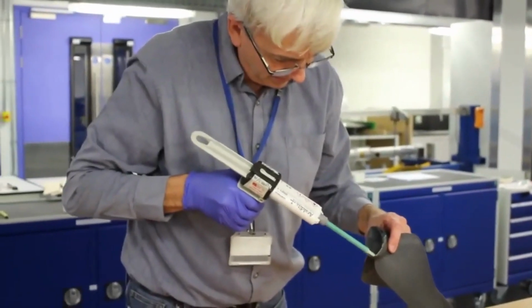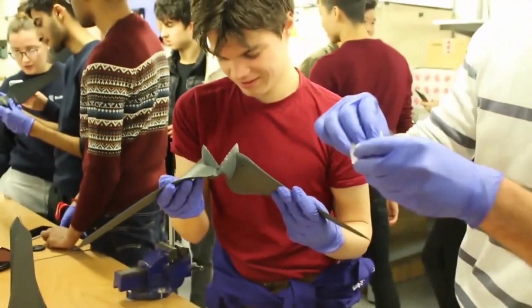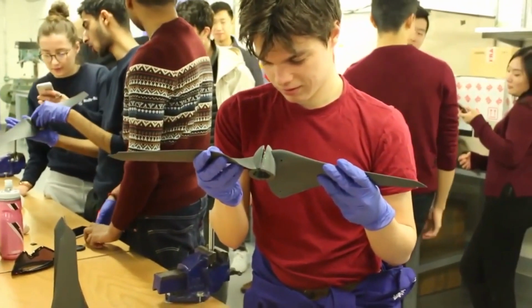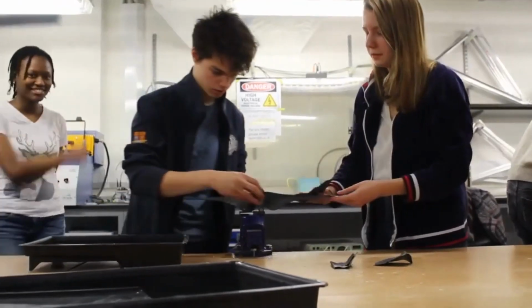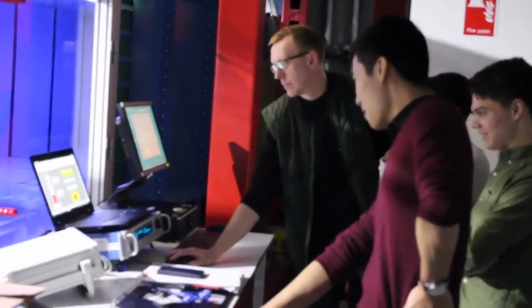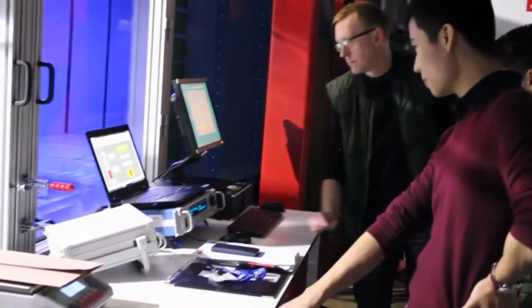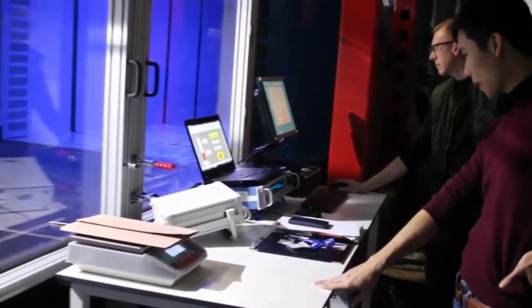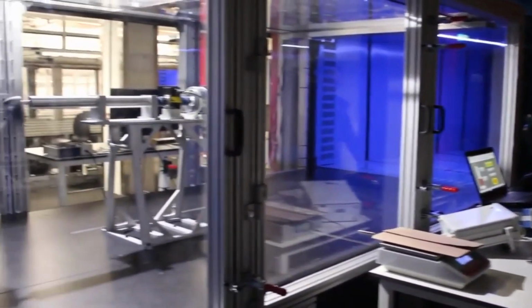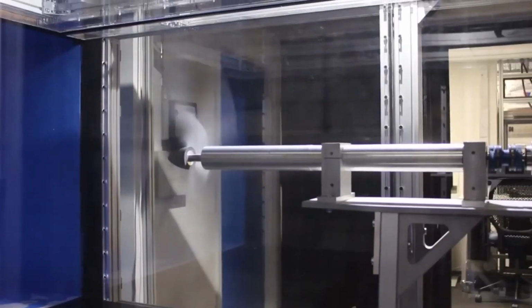Once the blade was removed from the bath, we glued the hub into the blade using an epoxy glue. We then sanded the blades in order to ensure a smooth surface, which will result in less skin friction drag. The turbine was tested in the 1.11 by 1.66 meter wind tunnel at 6, 8, 10 and 12 meters per second and was able to operate safely at all 4 test conditions without stalling or displaying noticeable deflections.